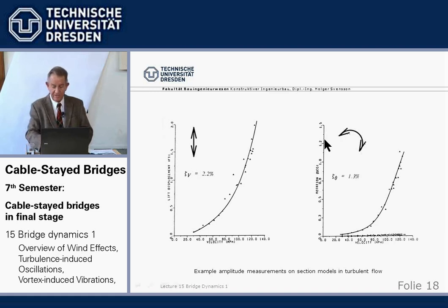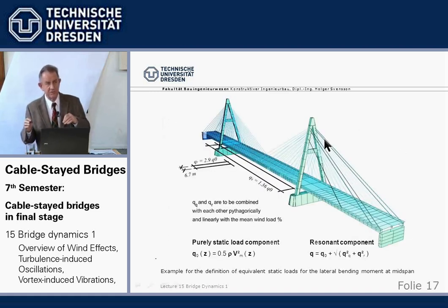And when we have these values corresponding to the wind, we can backwards calculate what equivalent static loads would produce the same deflection of the bridge which we have measured in the wind tunnel. And that can be, for example, for the base average mean speed, a constant transverse load, and then for the vortices, a variety of additional dynamic loads.